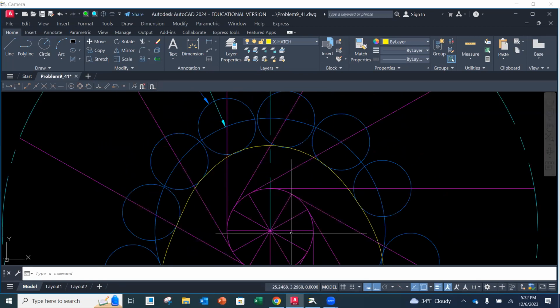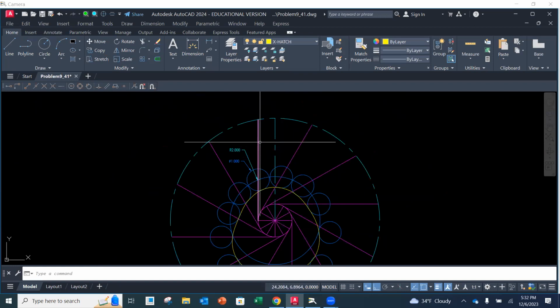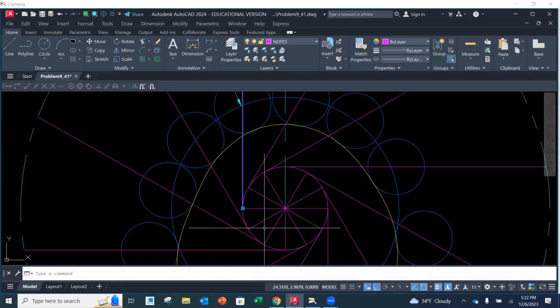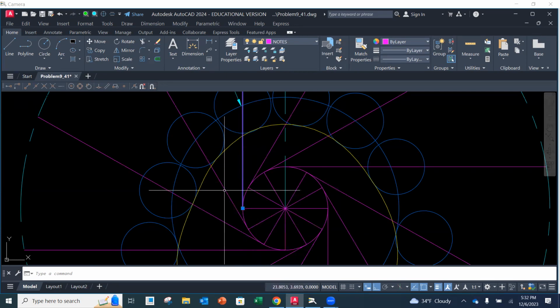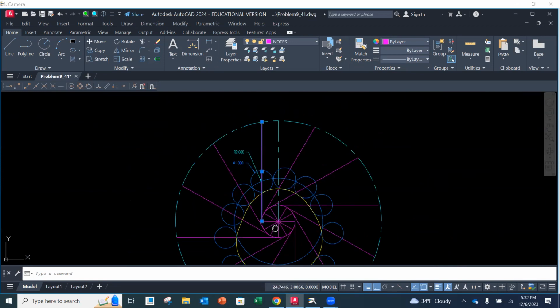Here you'll notice that here's my 0 degrees. I'm offset 3/4 of an inch to the left. So this is my 0 degrees here. And then I start, because I'm going in a clockwise direction, my 30 is going to be here. Okay, it's going to be counterclockwise. And then my line is perpendicular. And then 60, 90, 120. And then you do the offsets perpendicular.